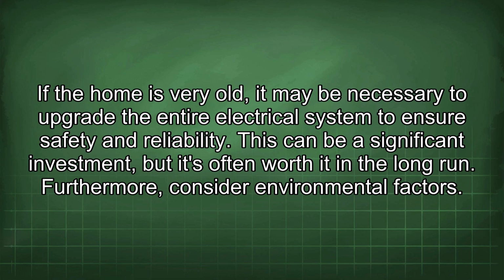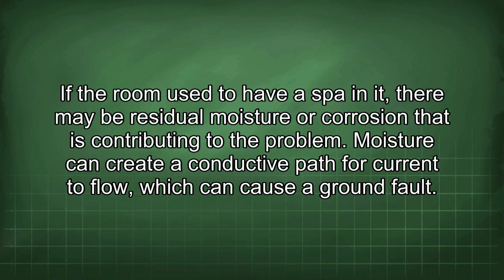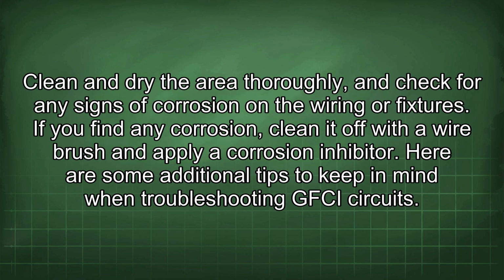Furthermore, consider environmental factors. If the room used to have a spa in it, there may be residual moisture or corrosion that is contributing to the problem. Moisture can create a conductive path for current to flow, which can cause a ground fault. Clean and dry the area thoroughly, and check for any signs of corrosion on the wiring or fixtures. If you find any corrosion, clean it off with a wire brush and apply a corrosion inhibitor.